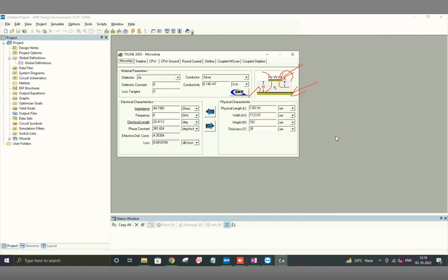So in that thing you're looking at, you see there are lines which are changing in dimension, and they are done for very specific reasons. Some of them are quarter wave transformers. The actual device which is made here is something called a rat race hybrid, which we'll study later on. The design has many sub parts. It starts as just a 50 ohm transmission line feeding in, and it changes impedance for some kind of impedance transformation. Then it goes into this circular thing, whose job is to split a signal into two in a specific way.